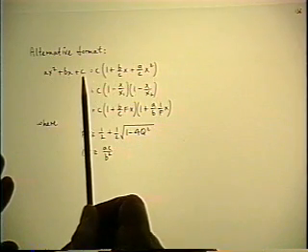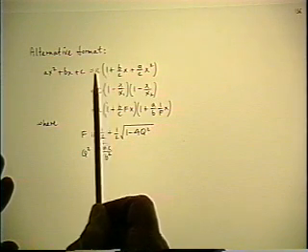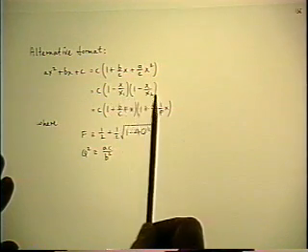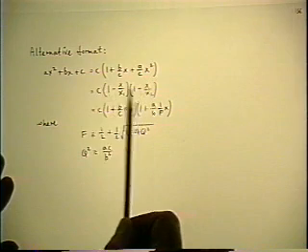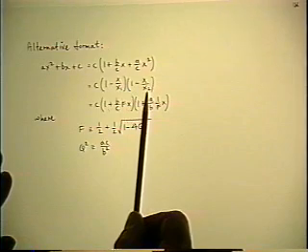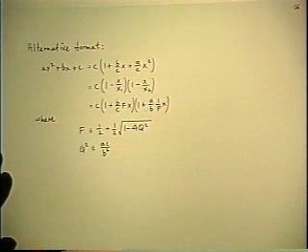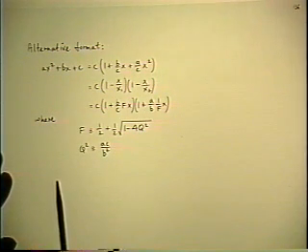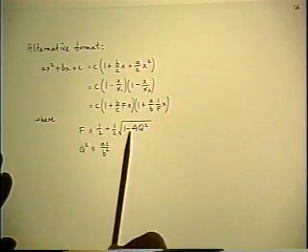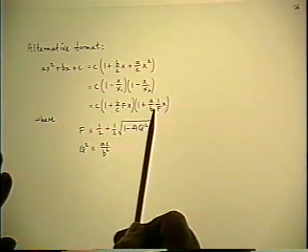So suppose I do the same thing with the quadratic. Now the leading term is not a but c. So I bring the c out front, and the consequence is that the roots x1 and x2 are now divided into the x term instead of being added. Just like we have in frequency response, where the x1 and x2 now become omega 1 and omega 2, which are the corner frequencies directly. And that's what we're interested in. Well, the formula for the x1 and x2 remains exactly the same in terms of the f and the q squared as before. And here's the direct substitution into the factors of the quadratic.